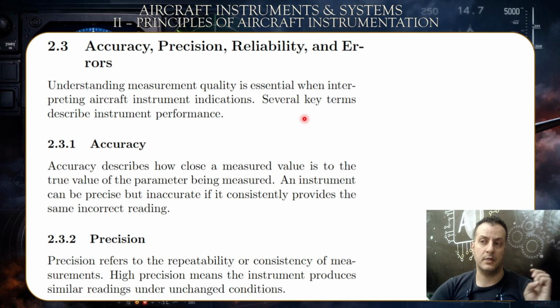Here is why we need to talk about these differences: accuracy and precision will affect the performance of the aircraft altogether. And it's not only for key instruments, it's actually everything. It's not only for the heading and the ASI, it can also be the engine power, how it's running, if it's measuring the EGT correctly.